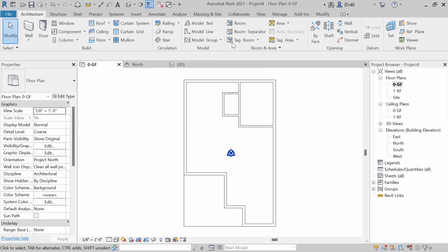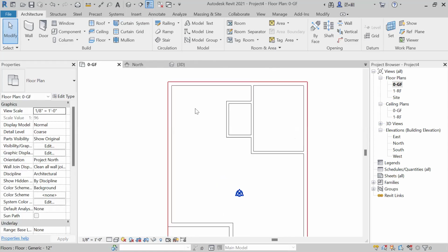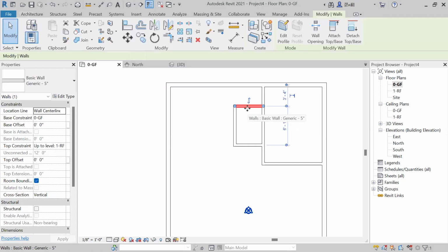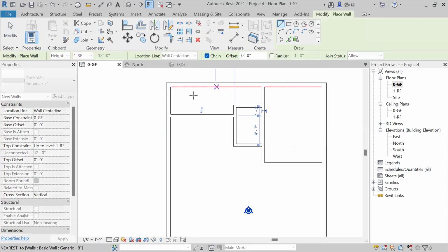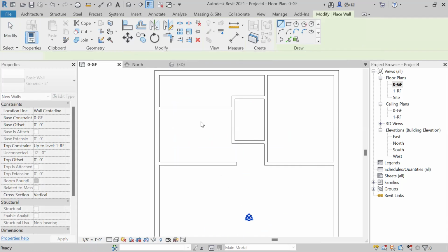Okay. So see, we have created the bedroom. Then we have created one toilet. Now let's say here I want to create one laundry. Same wall I want to create. Select this 5-inch wall, right click, the create similar option is given, create it. Suppose this area I have planned for laundry. And now I want to create a kitchen here. Let's say from here you can just draw one kitchen. Suppose this is my kitchen space. Okay. This is my kitchen area.